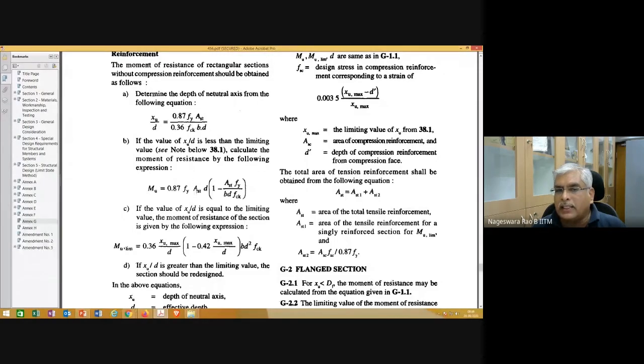Please note that in this it's not mentioned whether it's under reinforced or something like that. Wording is not used. But here it's directly given that moment of resistance is calculated with respect to steel. So that itself means it's under reinforced. So you please cross check whether this relation is correct or not, whatever is given in the code book, using whatever I showed you.